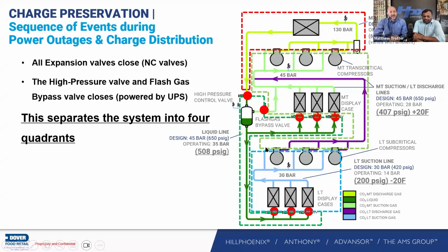So I guess in a power outage, it's one of the first things you want to take a look at. Yes, the first check is the valves on site. Check those valves. If they're not closed, then use the hand lever to isolate those. There's a magnetic tool you can use to close them shut, or there are bypass ball valves you can close. There are also bar valves too, right? You can make it 4 different sections, yes.